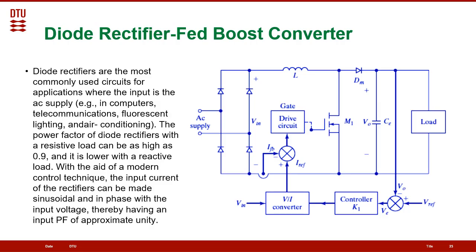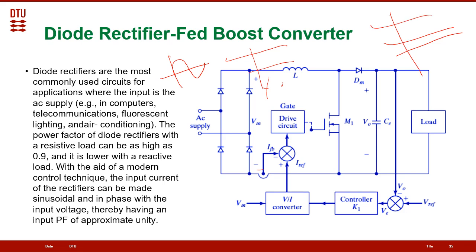So actually we have the AC source from the power supply, say 220 volt. Then before we can apply the AC signal to the converter, we need to do a rectification. So actually here we have a rectifier. This shows you that this is your input signal at this point. At this point here, your signal will be almost something like this, DC. Then here, if you use a buck or boost converter, you can increase or decrease the output voltage.